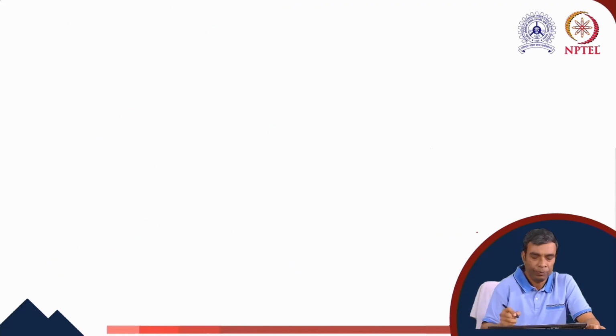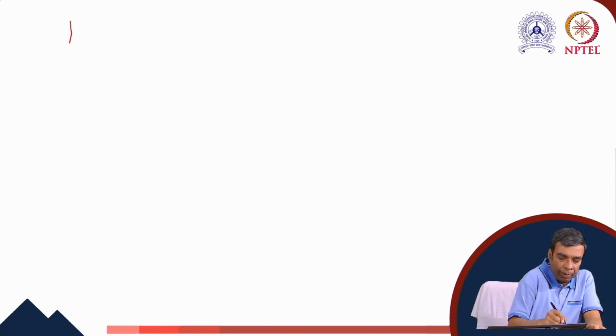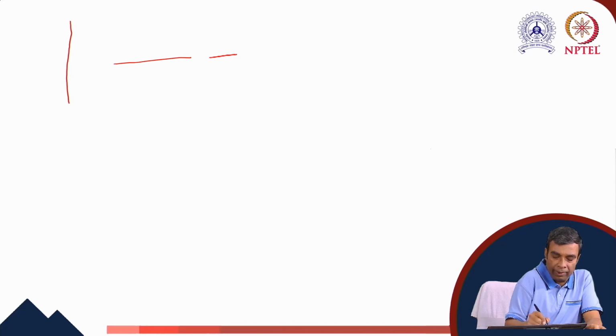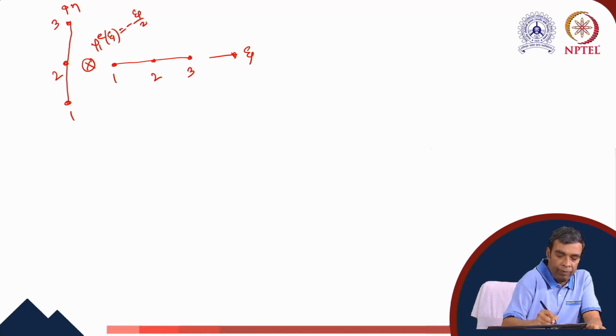So now we consider the quadratic bar element in the vertical direction and in the horizontal direction. This is the xi direction, this is the eta direction. Local nodes are 1, 2, 3. Here local nodes are 1, 2 and 3. This is the outer product. So here the shape function is psi 1 e xi equals minus xi by 2 into 1 minus xi.